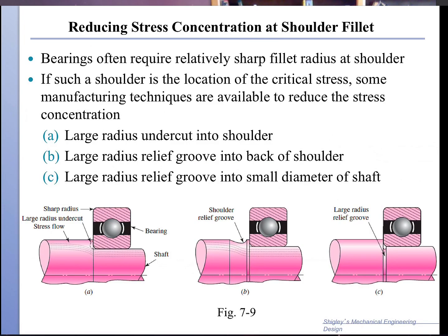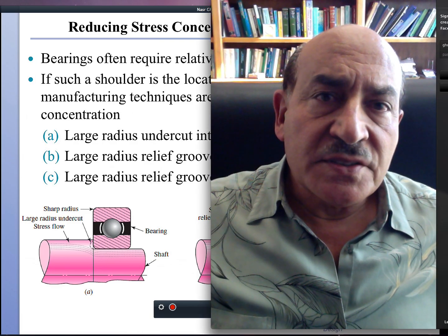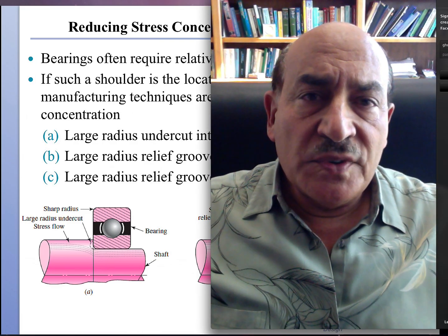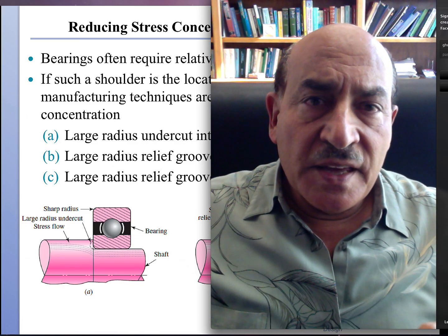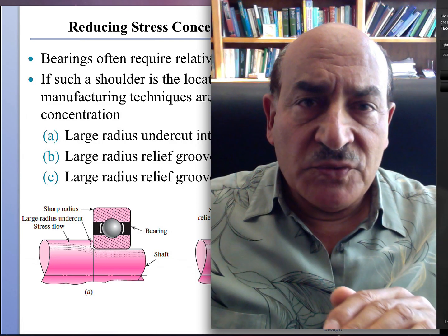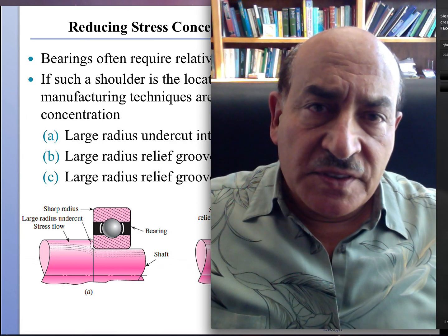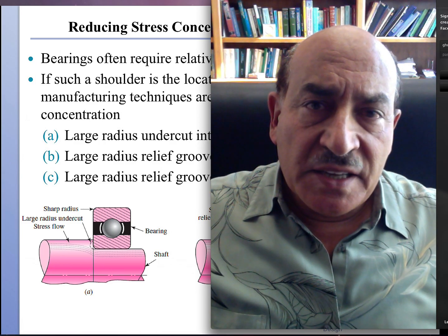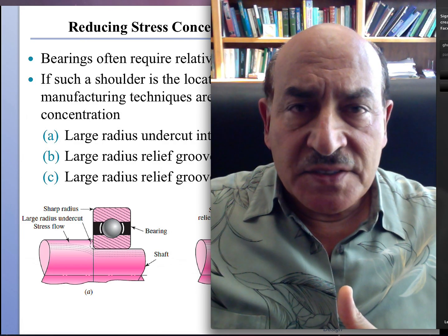If we look here to understand a little bit more about the idea of shoulders and stress concentration factors, as we move from the small diameter to the large diameter, we would like to avoid abrupt change in the diameter of the shaft, and that can be achieved either on the small shaft side or the large shaft side.